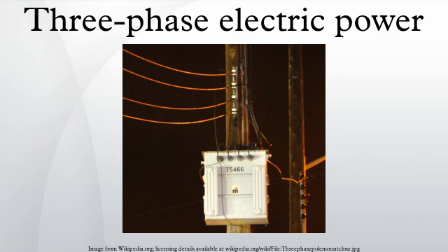Mechanical. One method to generate 3-phase power from a single-phase source is the rotary phase converter, essentially a 3-phase motor with special starting arrangements and power factor correction that produces balanced 3-phase voltages. When properly designed, these rotary converters can allow satisfactory operation of a 3-phase motor on a single-phase source.